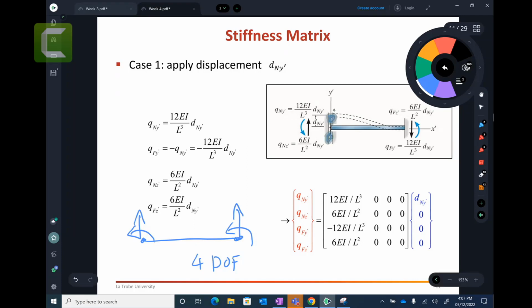So what these sliders will do is allow this point to go freely up and down. Are you with me? All other degrees are fixed. This one is fixed because this point cannot rotate. These are fixed here because they cannot go up and down or rotate. So at the moment, only this point can go up and down. So I fix this one. This is a slider, so this point can only go up and down. Right? This is the first thing I did.